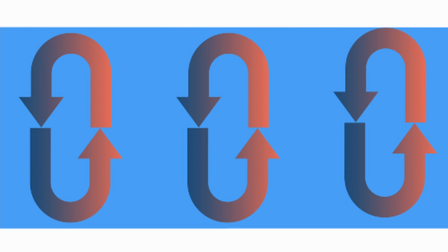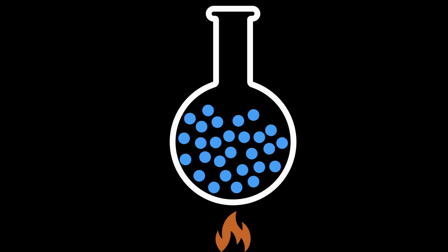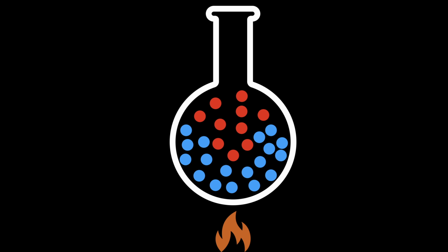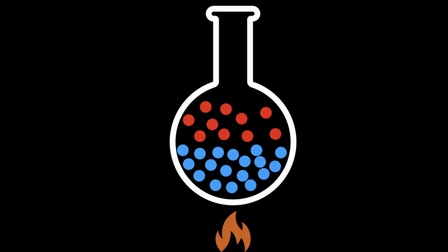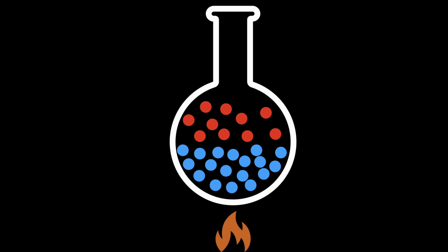Convection works and takes advantage of density changes in a medium when its temperature changes. When a fluid is heated up, its molecules become more active and spread apart, making it less dense. The hotter, lighter molecules will then rise, and the cooler, denser molecules on top will replace them. The denser molecules will also start to heat up, spread apart, and rise up. This process, also known as a convection current, continues indefinitely as long as there is a heat source present.